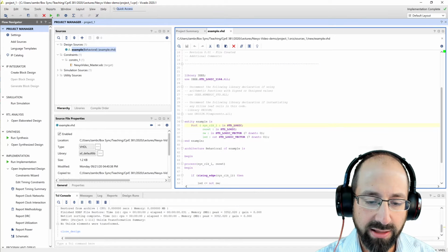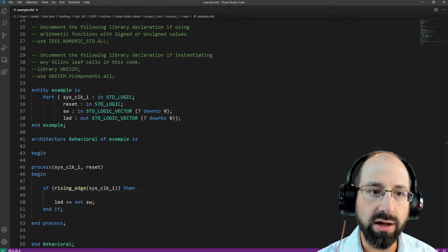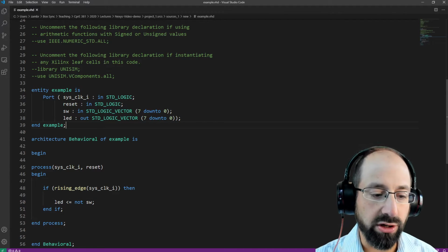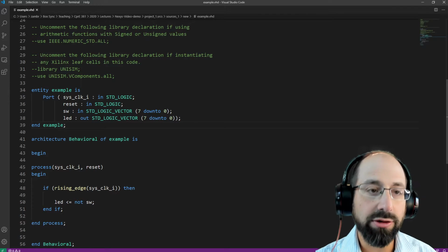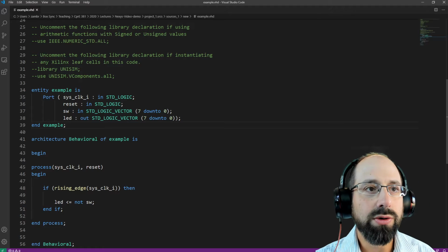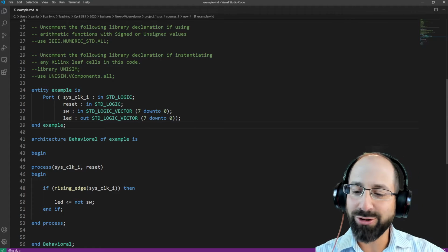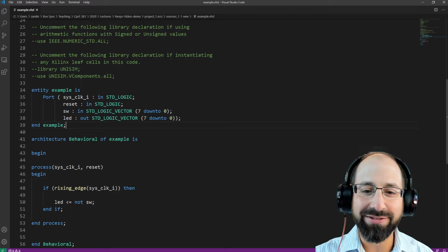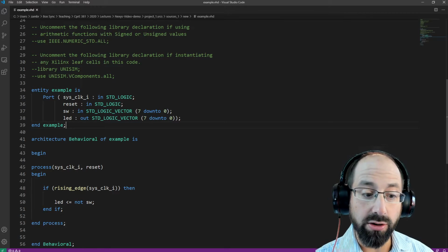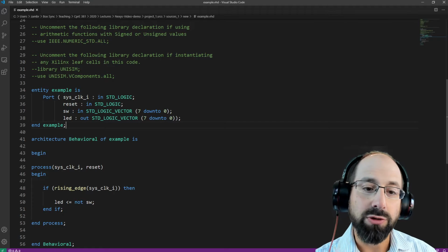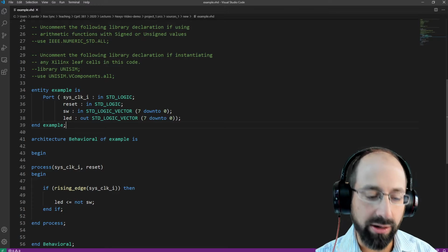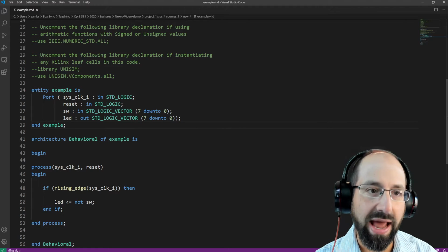I know that that file in Vivado itself is a little hard to read, so I also have it open here in Visual Studio Code. And it was very simple where we started off, right? If we were to draw out this design, and I think you should all be able to at this point in the semester. Technically, that's backwards. Technically, we should be drawing out our design first and then developing the code for it. But we just threw some very quick code together. But now we should be able to look at that code. Or another way to think about it is we should be able to analyze someone else's code and get a good feel for what type of hardware is being elaborated on the back end.